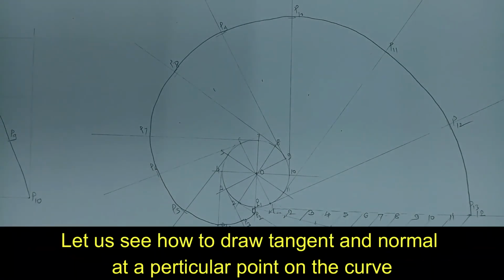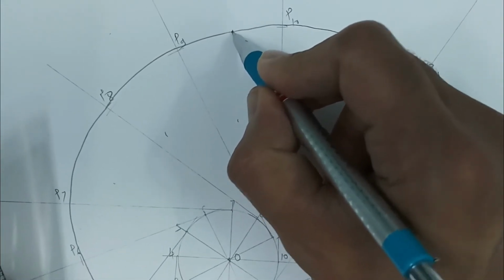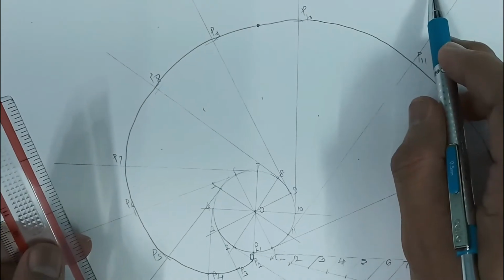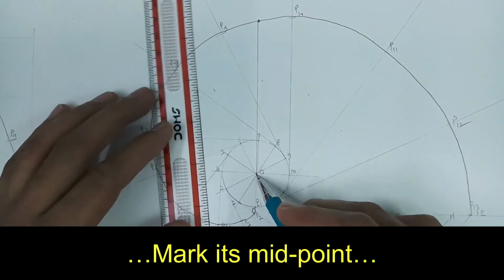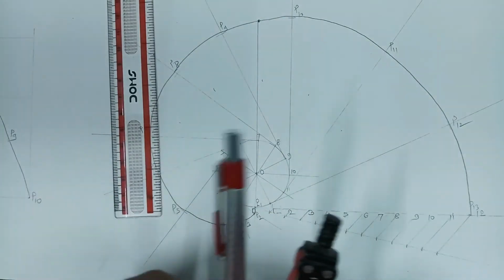Now here the extension of the question may be to draw a tangent and normal at a particular point on the curve. Let us say this is one point on the curve, and at this particular point I have to draw a tangent to this involute and also a normal through this point. Join that point with the center of the circle, then mark its midpoint.